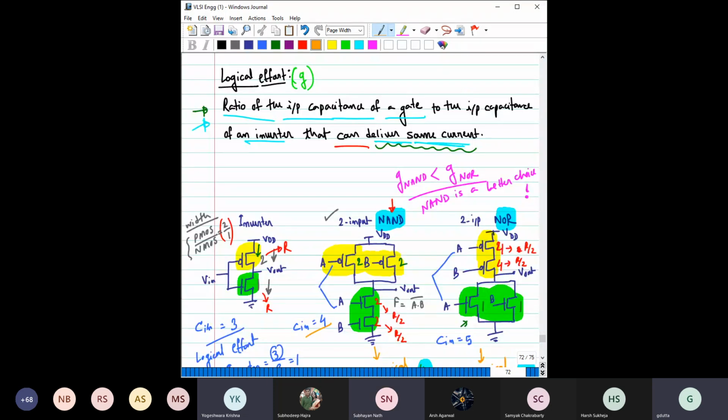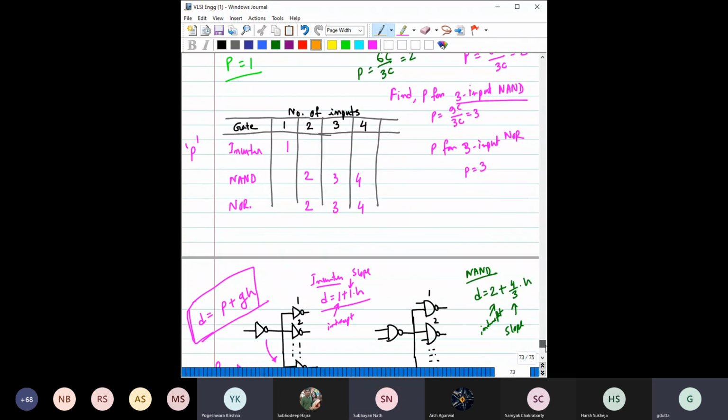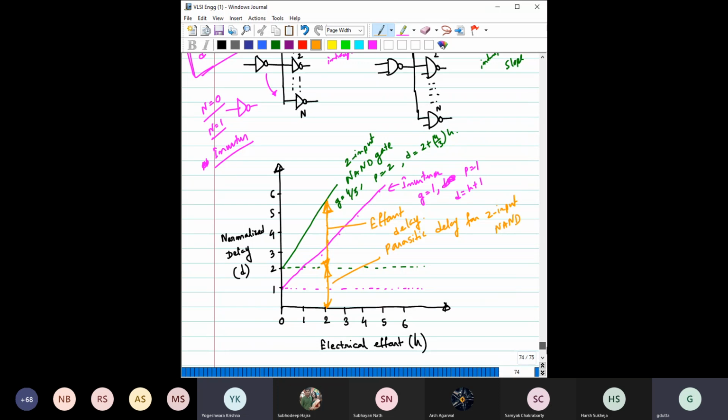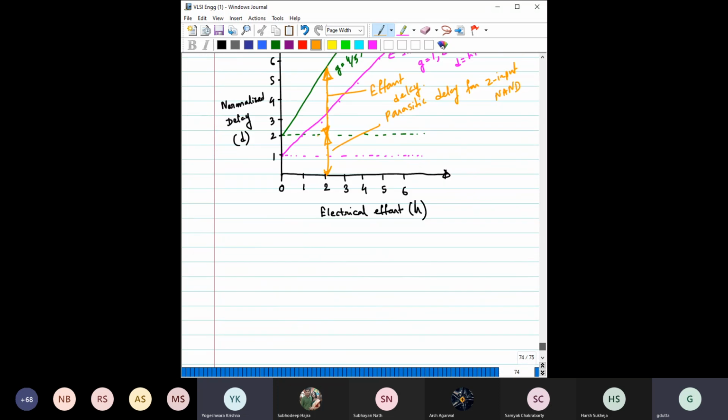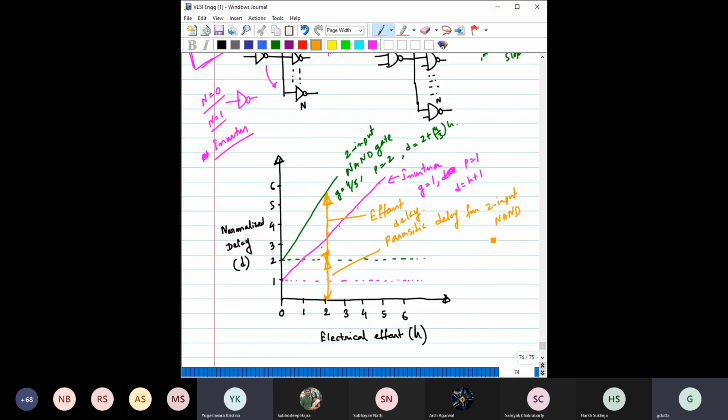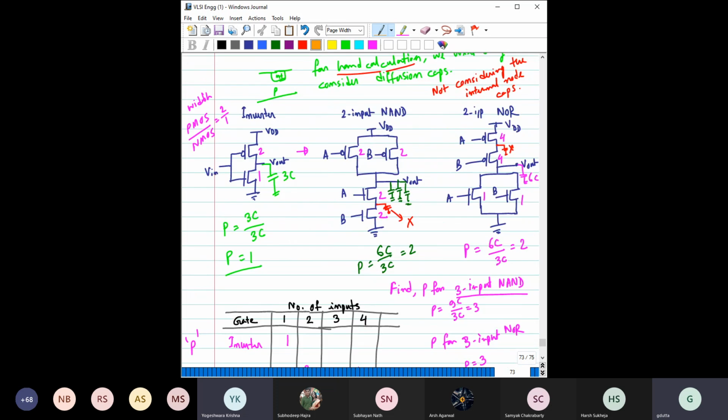That is the effort delay. Shubham, actually it is not the Elmore delay. We will be covering the Elmore delay later, and there we will also consider the internal node capacitances. I was talking about the graph, that the effort delay basically changes with n, or the fan out.